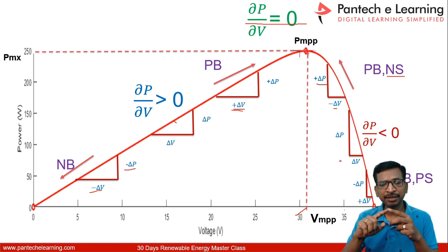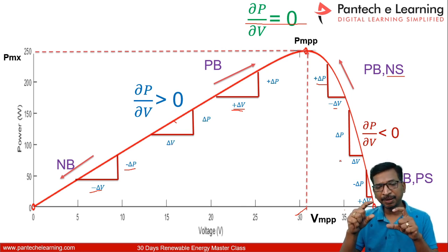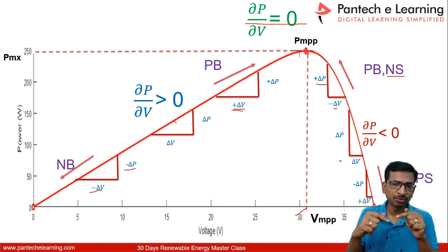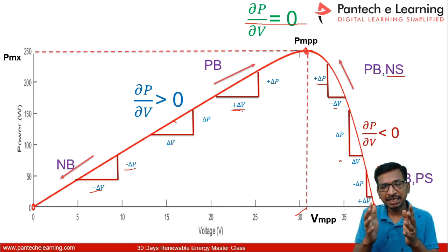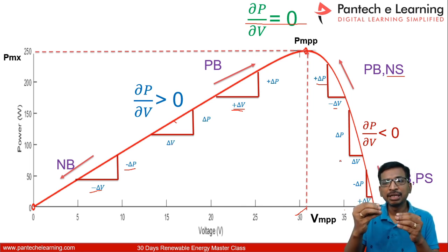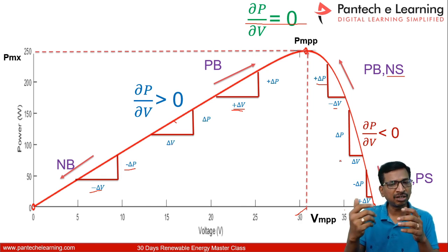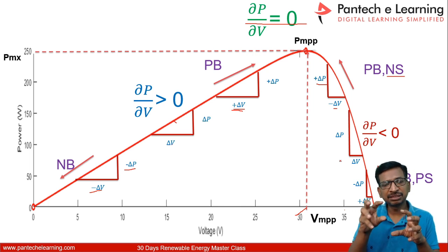One is called the power. Ultimately, we need the maximum power. So the power, and with the sample time, that is the n minus 1 sample. Now the fuzzy logic can understand the power with respect to the n minus 1th power: nth power, comma, n minus 1th power. If you apply these two parameters to the fuzzy logic, then the fuzzy logic will automatically calculate these values.